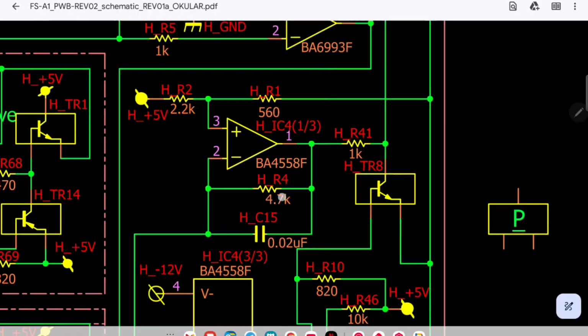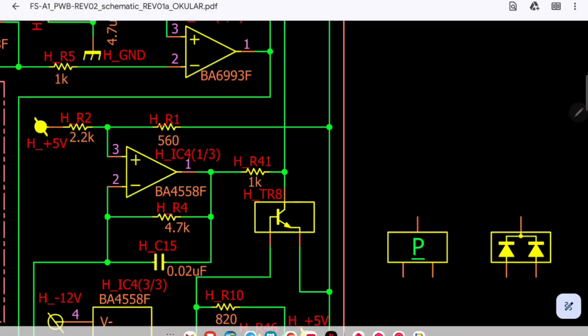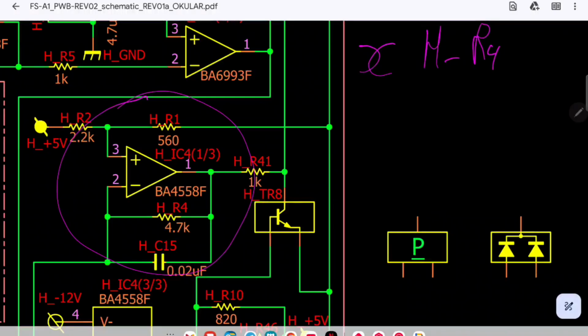And by the way, I haven't forgotten about our friend capacitor C16, so let's go for it. You can think about a capacitor as a variable resistor whose impedance goes down with the frequency. If you remember, in the calculations we did, we found that the gain of this amplifier was proportional to resistor R4.